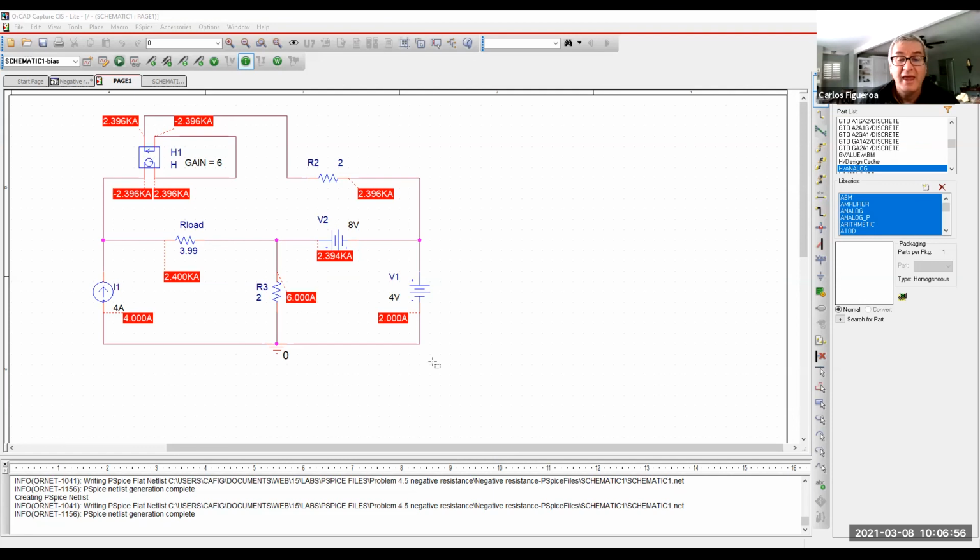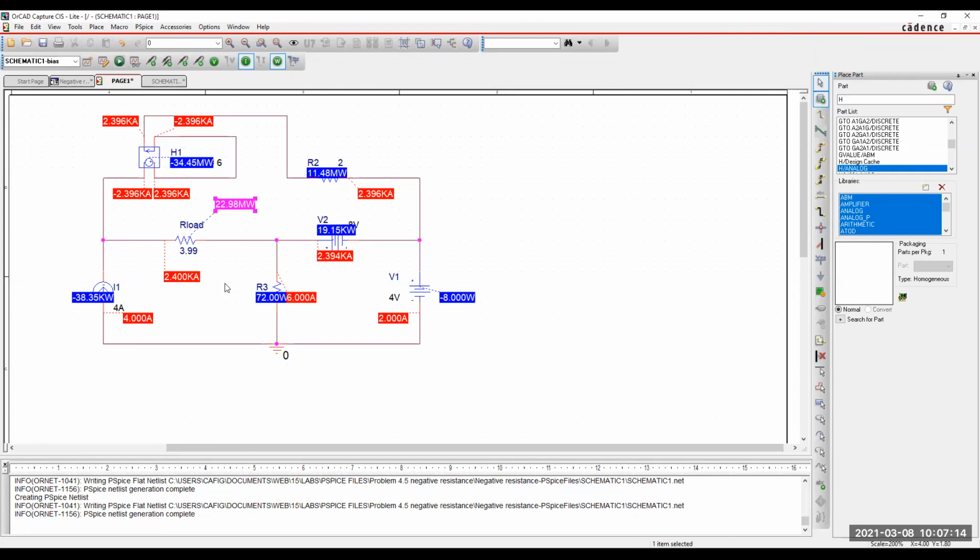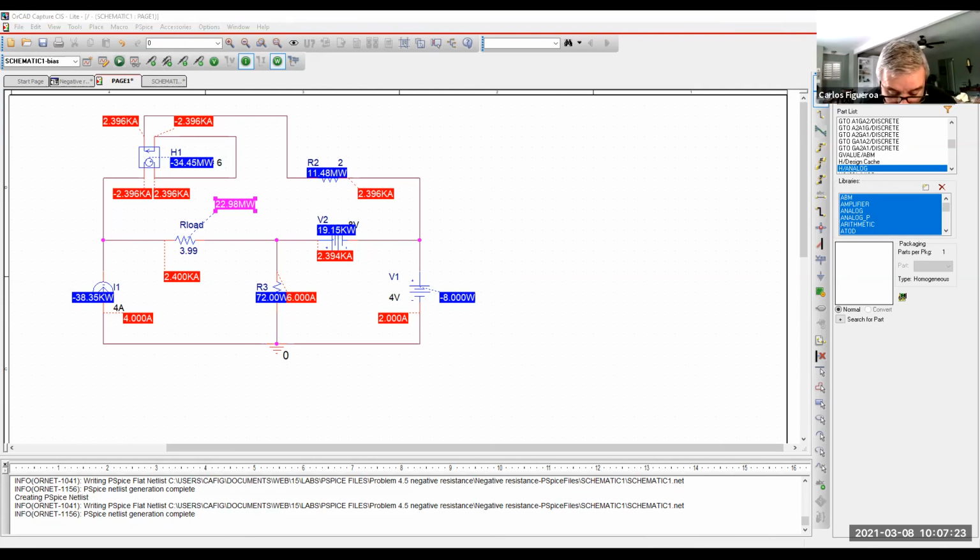So you're seeing that in this situation you're getting these mega currents. And if you look at this, maybe we calculate the power. Dude, look at the power, right? 23 megawatts across that resistor. What resistor is going to take megawatts of power being dissipated? It can't. It's not possible. And so that's the effect of the Thevenin resistance here, right?